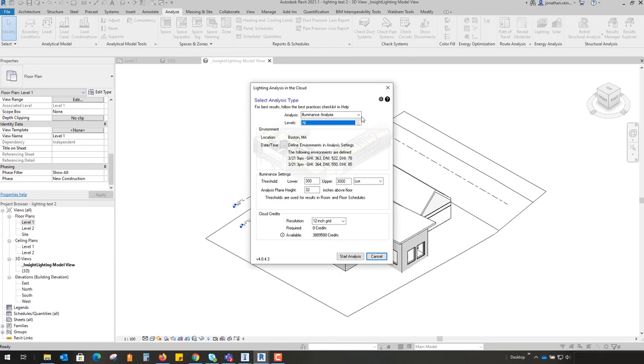That's then going to pull up another dialog box, and you can perform a series of different tests. So you can perform an illuminance test, which is just going to test the inside, the amount of daylight access to a room, the daylight factor, which gives you a percentage of daylight factor over the number of sunlight hours across a whole year or annually. Daylight autonomy, so how autonomous is a room to light itself just from windows without any lighting. And then there are a number of industry standards such as the LEED 2009, and then there's LEED version 4 as well, and you can also measure solar access to a particular internal space as well.